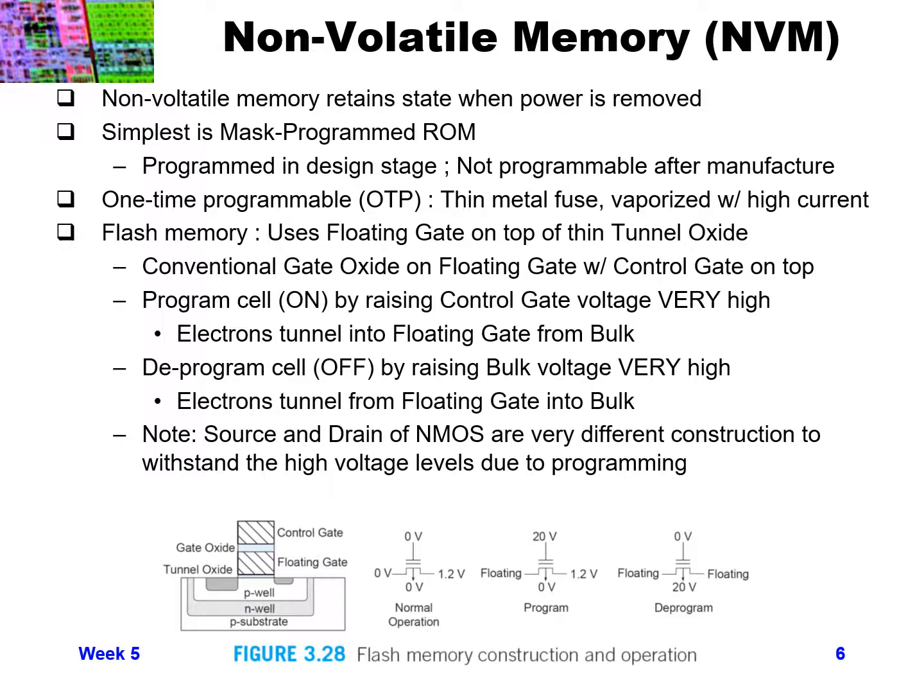This high voltage will cause your floating gate to get pulled up, and as that gets pulled up to a higher voltage, the thin tunnel oxide under that floating gate can actually allow carriers to tunnel through it, and the floating gate gets basically charged up or discharged depending on what you did with your control gate, whether you put a high voltage or a low voltage there.